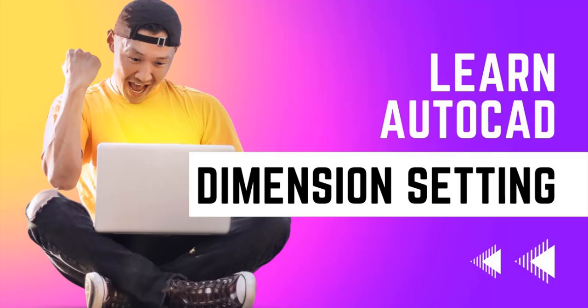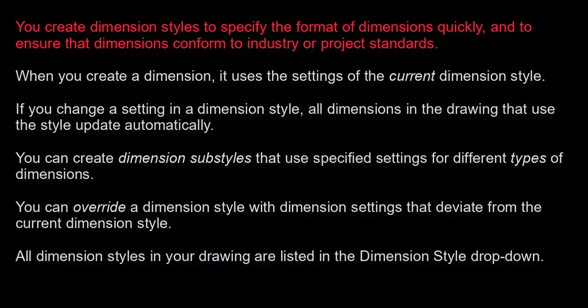Dimensioning. A dimension style is a named collection of dimension settings that controls the appearance of dimensions, such as arrowhead style, text location, and lateral tolerances. You create dimension styles to specify the format of dimensions quickly, and to ensure that dimensions conform to industry or project standards. When you create a dimension, it uses the settings of the current dimension style.